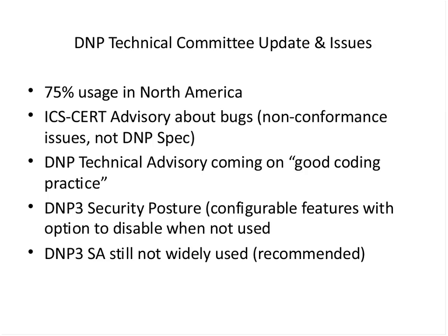And the DNP3 secure authentication is still not being widely used, and the technical committee folks recommended it and told me to tell all of you that please use it. It'll only help you. It will reduce some of those risks that are associated with networks today, especially heterogeneous networks, because it provides you a very secure channel from one end of the application to another.